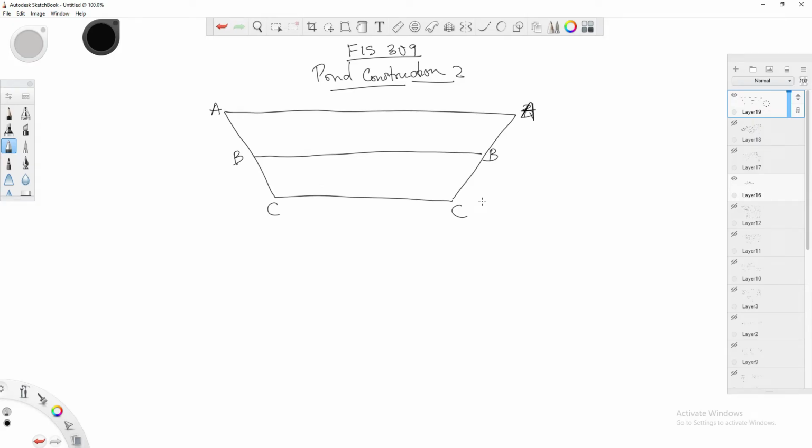So now, how do we get the volume of excavation? That's the question. Firstly, you would have been given the base area. Usually the base area, like I said, is always given in the question. So let's take, for example, the base area is 20 by 40, or any area given is usually the base. So that means this place is 20 by 40, in meter square.